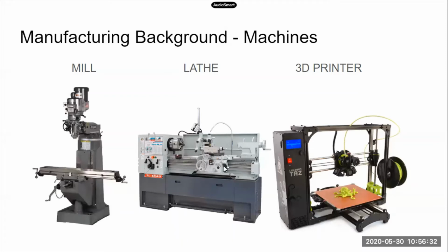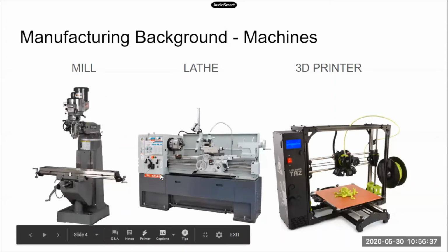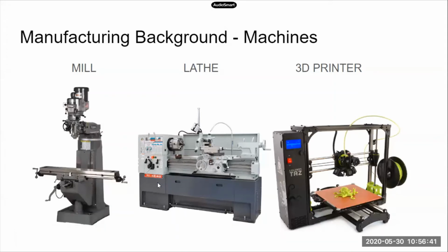And then, yeah, this is also manual. You do have this thing called auto feed in some manual machines, where basically you flip a switch and the tool will move in a constant path at whatever rate you set it to, which would be dependent on material and such.